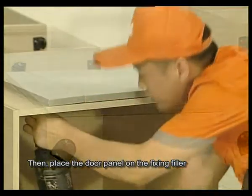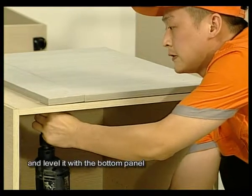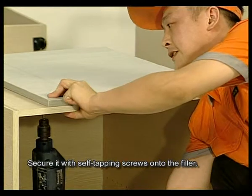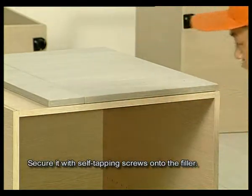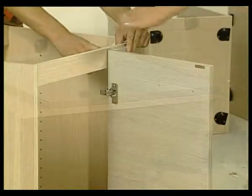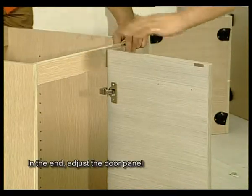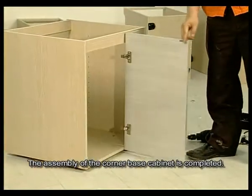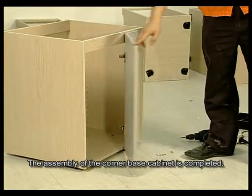Then, place the door panel on the fixing filler and level it with the bottom panel. Secure it with self-tapping screws onto the filler. In the end, adjust the door panel. The assembly of the corner base cabinet is completed.